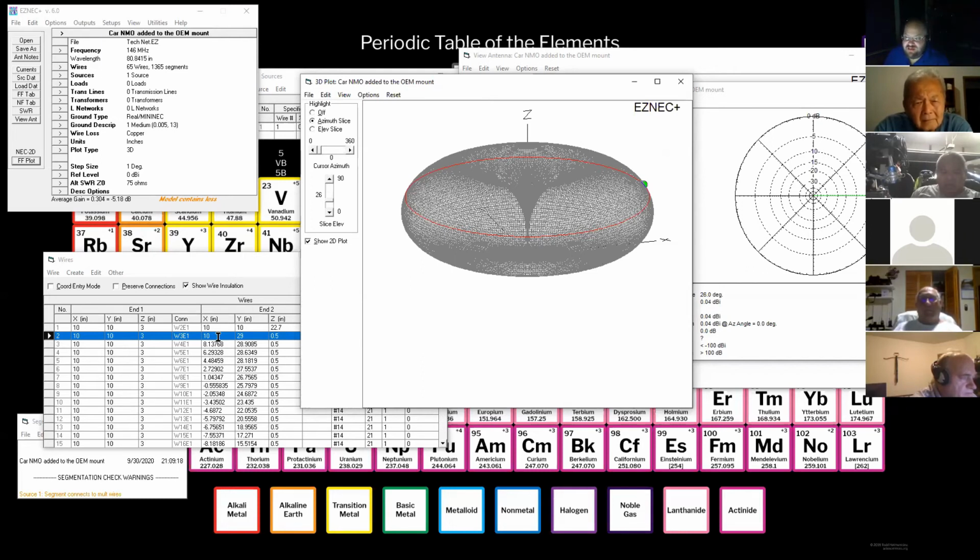Those of you who got to see my Grid Madness antenna, you saw the design in here, and then you saw what the thing looked like on the end of the boom in front of the corner reflector. It gave me an idea of where to cut it. And in that case, I cut everything 1/4 inch long and then scaled it back because I had worked on that design for a while.